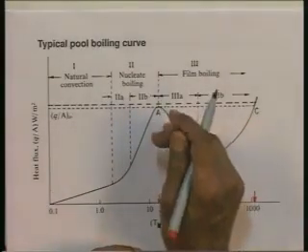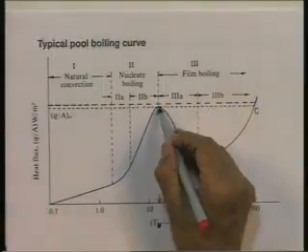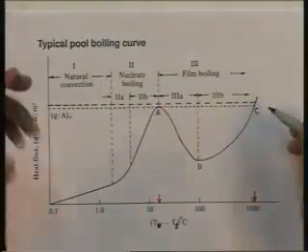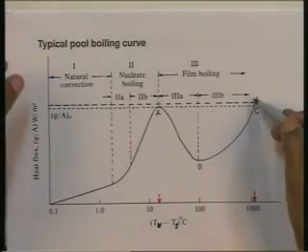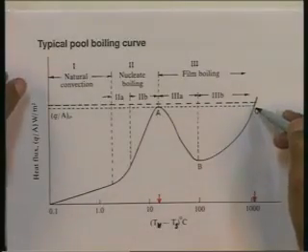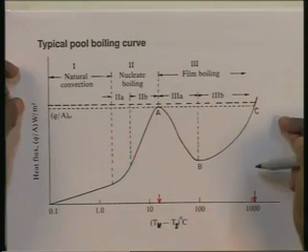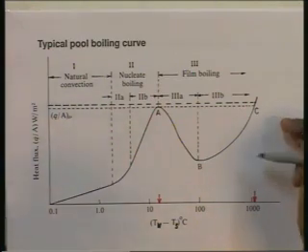And in practice, wherever heat flux is the controlling factor, and it is in many situations, it is important not to exceed this value in order to see that the wall temperature does not go above some safe value and does not get damaged.